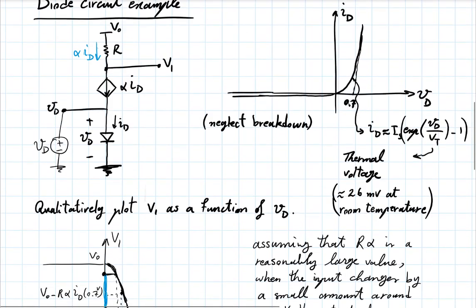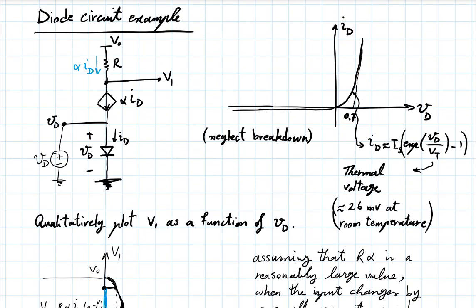And this is, in fact, a circuit that you would call a common emitter amplifier. And we will see that more formally. But this is a picture that does not capture everything that a bipolar junction transistor does and all its limitations. This is a simplified picture. But it's a picture that captures a very, very important chunk of the behavior of the BJT, and in fact, the chunk of the behavior that we are most commonly interested in. Okay? So if you understand this circuit, you already understand a good deal of the operation of the BJT and its use in circuits.